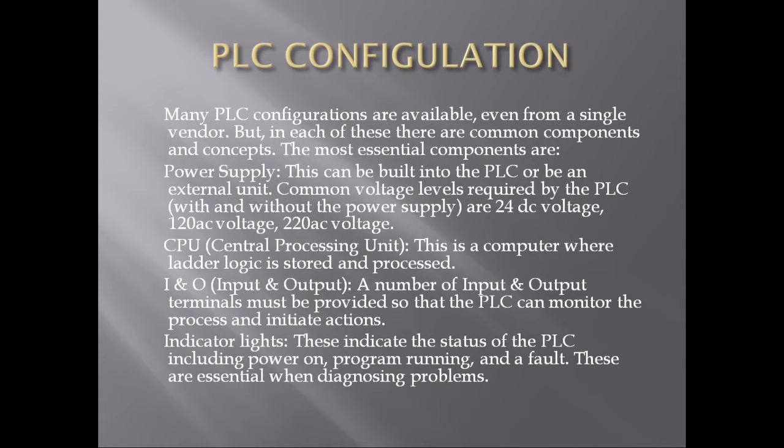Many PLC configurations are available, even from a single vendor. But in each of these there are common components and concepts. The most essential components are: power supply. This can be built into the PLC or be an external unit. Common voltage levels required by the PLC, with and without the power supply, are 24-volt, 120-volt, and 220-volt.